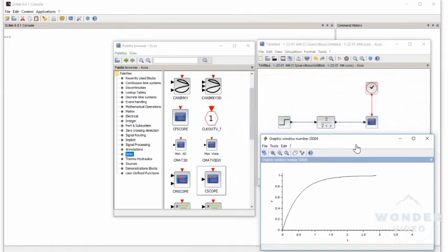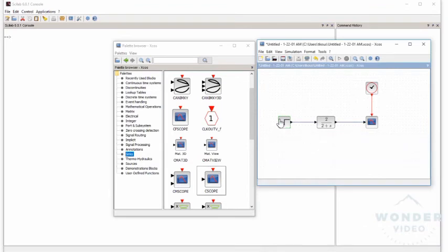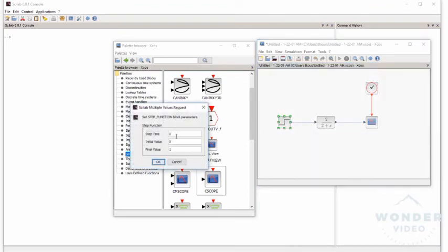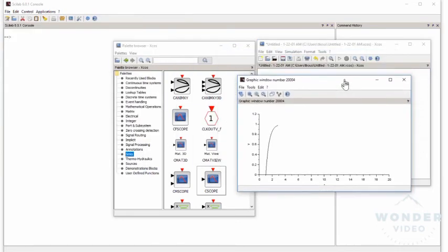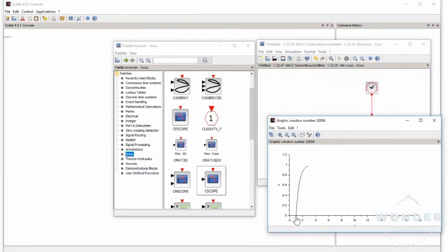You can do a little bit of variation. For example, we are applying the step function here at 0. You can apply it at 1, with a delay of 1 second, so the graph will start from here. So let's close this. Now if we set the step time to 1, for example, and do the simulation again, as you can see, our step function is now applied at time 1. So it's a delay of 1 second.